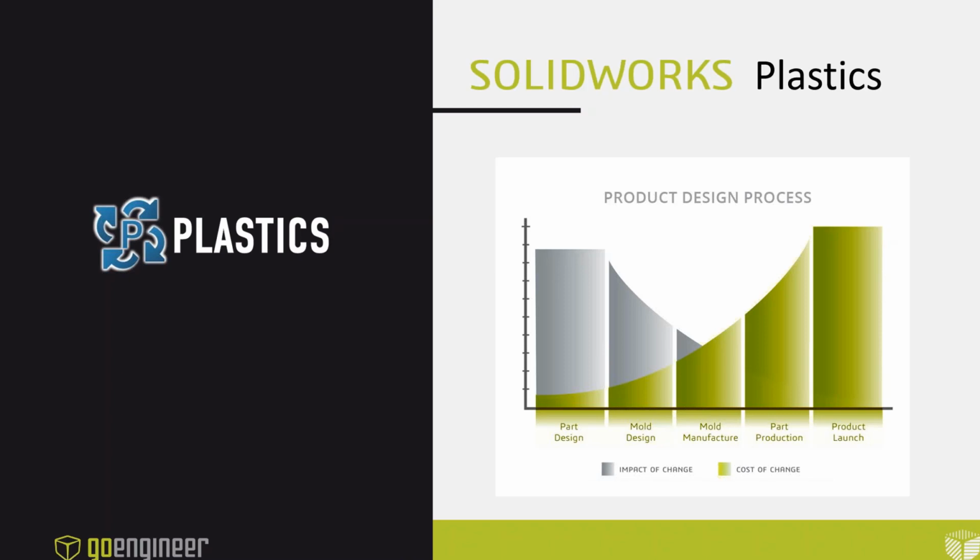But then as this project transitions through the manufacturing process and goes from design to approval, and then goes to tooling, and then goes to injection molding, as we move down that line, the cost to change drastically changes, right? A small change on the mold is extremely expensive in comparison to a small change on the part design. So when you have to change the mold somehow, things get expensive.